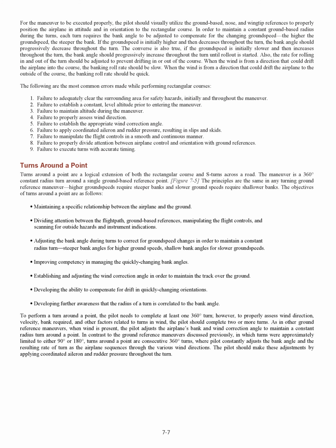Improving competency in managing the quickly changing bank angles. Establishing and adjusting the wind correction angle in order to maintain the track over the ground. Developing the ability to compensate for drift in quickly changing orientations. Developing further awareness that the radius of a turn is correlated to the bank angle.